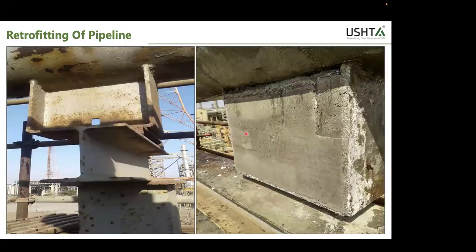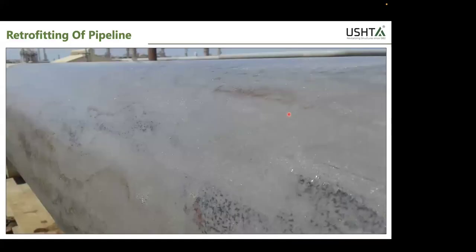Later on, all the saddle supports which were there had sharp edges, so we filled this cavity with micro concrete. You can see on the right, so that we can continue our fiber and connect that as well. Then we applied a putty to surface this. We need a smooth level because there were dentations from the corrosion on the pipes. There were a lot of pockets which had developed, multiple, so those had to be leveled first.